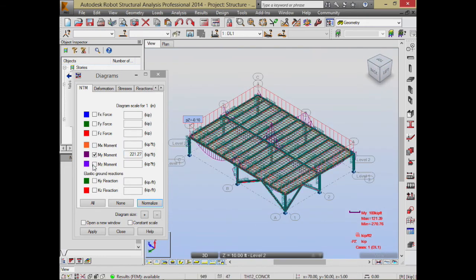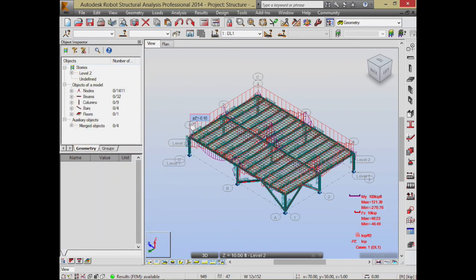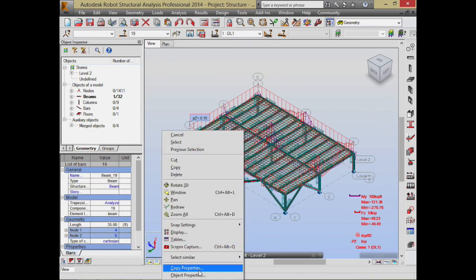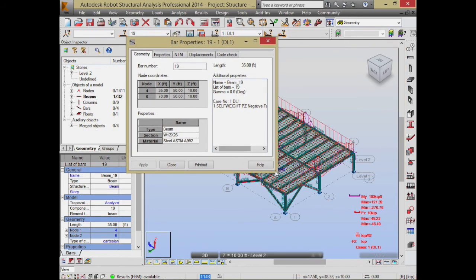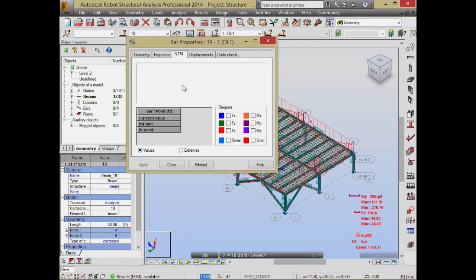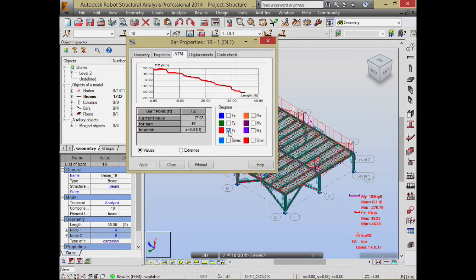We can go through and show the shear forces if you want to in any of the different members in whatever direction you want to go through and show. But let's go ahead and do it probably a little more systematically. It's probably the better way to do this, to go through and choose a bar and just choose its properties. Okay. And you can start to see in an individual bar really what's going on. So in terms of showing, for example, the values of the shear and bending moment, you can get that across its length. That's really what the values are as you go through.